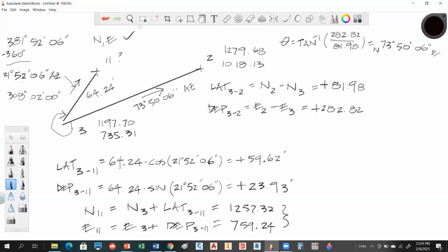We'll do the one at 4, because if you notice, at 4 you're sitting at 4, backsighting 3, foresighting 12. You're actually turning that angle counterclockwise. As I've said in class, you wouldn't typically do that, because you wouldn't have some angles to the left and some to the right. That's just going to be a place for mistakes.